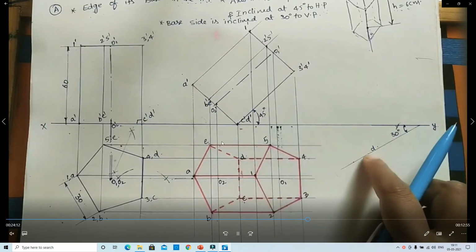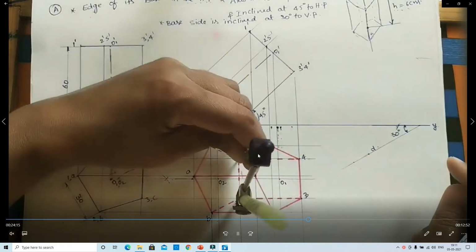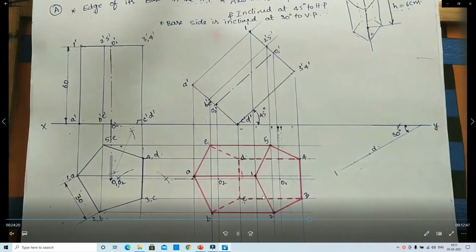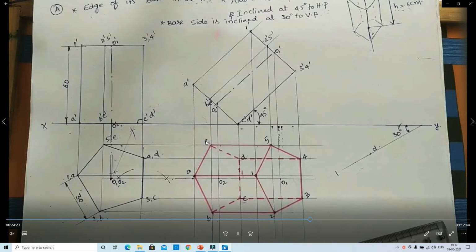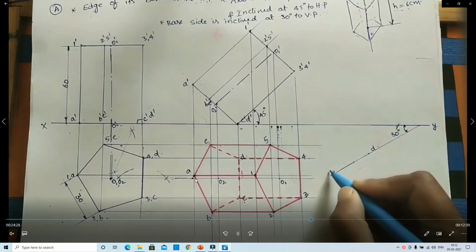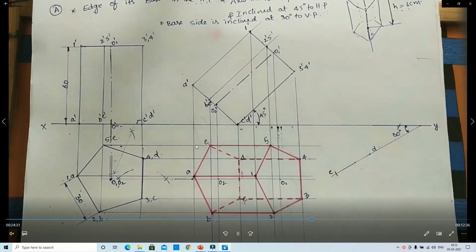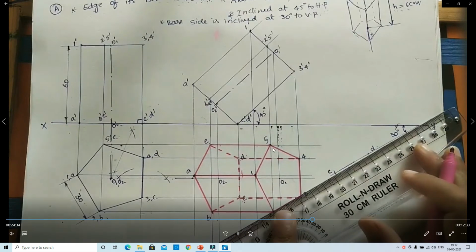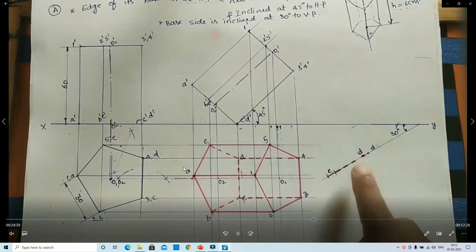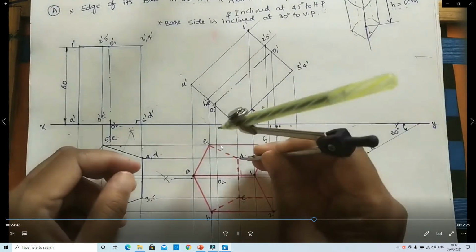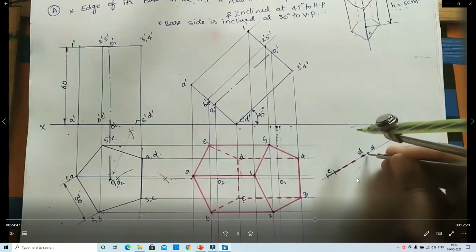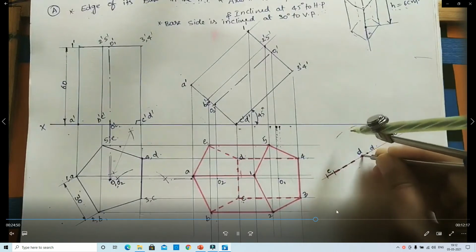Same then, here, in case you find it tough to draw this type of pentagonal prism with axis inclination, first you take the total length of the box, a horizontal line, this 1, 2, 3, 4, 5. This is the total box. Then after the total box you draw the axis distance. Then you identify the points of this top view. Here also you identify those points, same here. Okay.